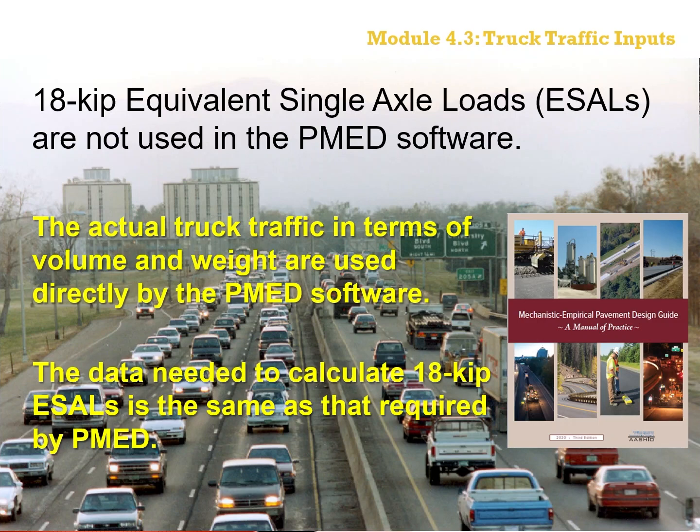In fact, the software does calculate the number of 18 kip equivalencies throughout the design period. So even though it looks like there's a lot of data required to simulate truck traffic, in actuality it is basically no different than what's required for the 1993 AASHTO pavement design procedure or the empirical pavement design procedure.